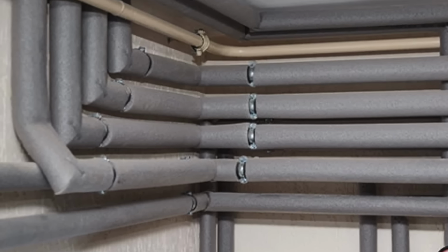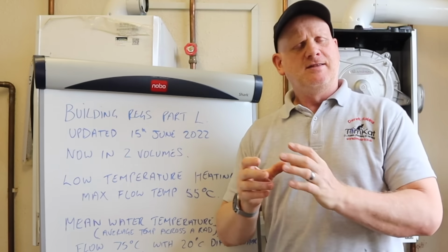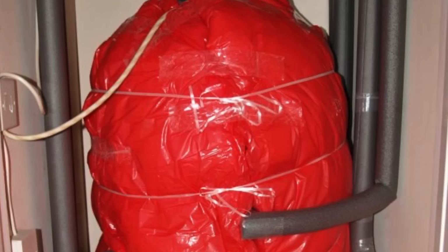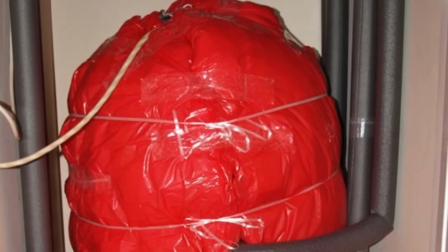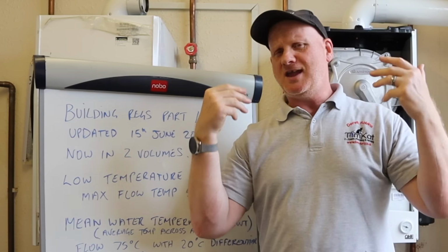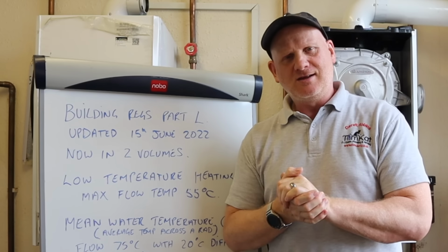If you've got an airing cupboard with a cylinder, remember it's a cylinder, not a tank, then all the pipes coming off there need to be insulated to stop all that heat loss and wastage of heat going to your cylinder. Now if you open up your airing cupboard and all this heat hits you and your towels are lovely and warm, then you're wasting a lot of heat.